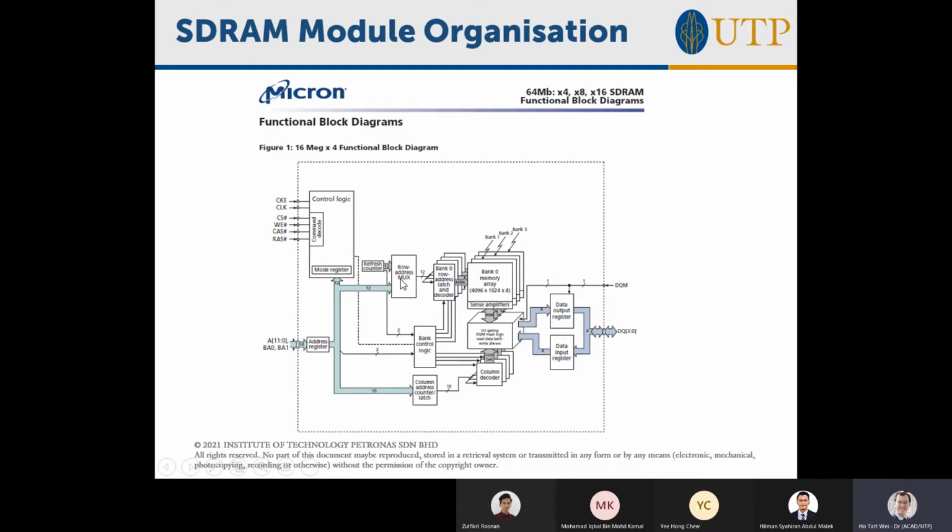The counter allows us to count to go to different rows, and we're also able to do a burst from the column decoder here. And this is just a multiplexer to go either you're sending data out or writing the data in here. But there is a state machine, a controller here, that will receive commands and then decide what is the operation. And we're going to go through this in some detail.